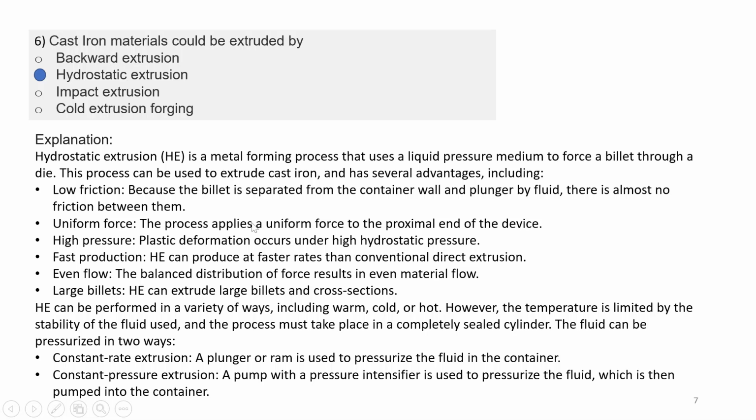There is uniform force. The process applies a uniform force to the billet. High pressure, so plastic deformation occurs under high hydrostatic pressure. Fast production, so hydrostatic extrusion can produce at faster rates than conventional direct extrusion. Even flow, the balanced distribution of force results in even material flow.